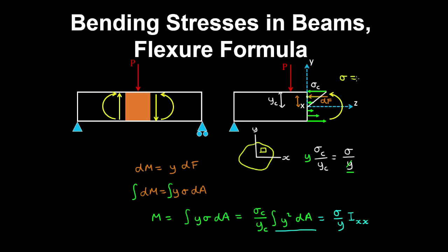So therefore we can write the bending stress as M multiplied by y on the second moment of area. And because we want tensile bending stresses to be positive, at a negative y value along that section, and where the sagging moment is positive, then positive by negative will give a negative stress. So to make the tensile stress positive, we'll put a negative over here. So where y is positive, we have the sagging moment causing compression, and because M and y will be positive in this case, we have the compressive stress being negative.